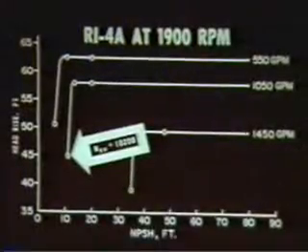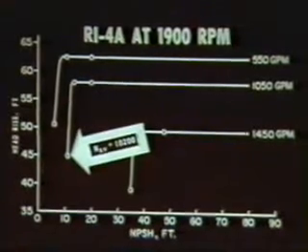Note the interaction of the rear channel cavitation with the splitter vanes. The leading edge cavitation appears unrelated to the rear channel cavitation. A loss of hydraulic performance has resulted from cavitation entering the splitter flow channel.